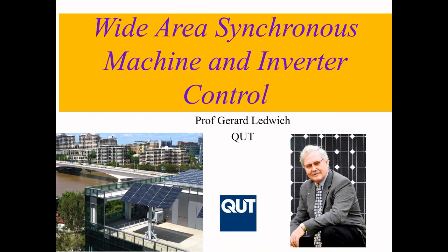Traditionally, the detailed dynamic controls would have been the responsibility of the transmission company. And so I suspect that would not be a bad management process. If we wanted to know, well, what is the angle of Central Queensland, there may be 6 PMUs in the area that we need to amalgamate to come up with the best representation for then the appropriate broadcast.